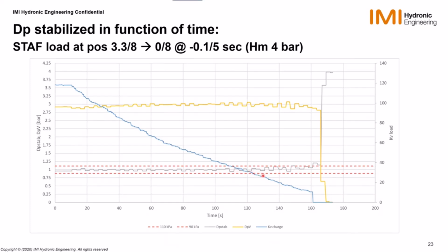At some point when we close the load here, there is a point where the next setting of the STF, you get fully closed. So it goes fast. You are almost closed and then closed. And you see that, unfortunately, the electronic delta P controller is not able to close fast enough. It follows at the speed of the actuator. It is closing, but unfortunately, because it is closing slower than the load, the delta P on the load is increasing to the total available differential pressure, which was 4 bar.